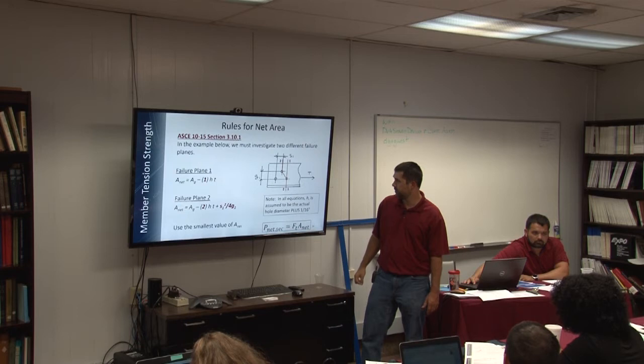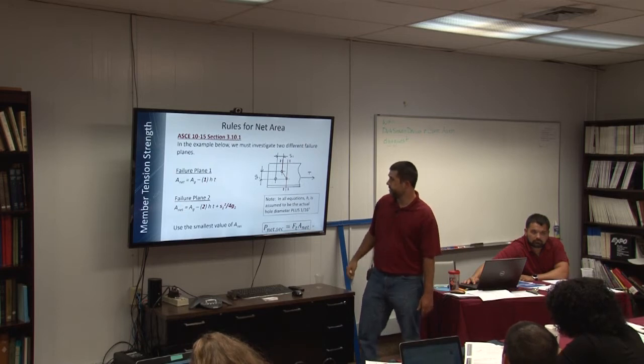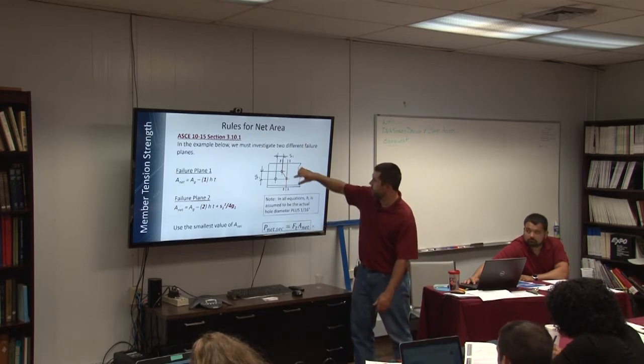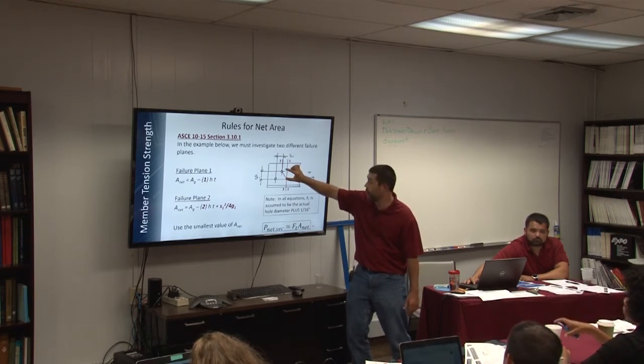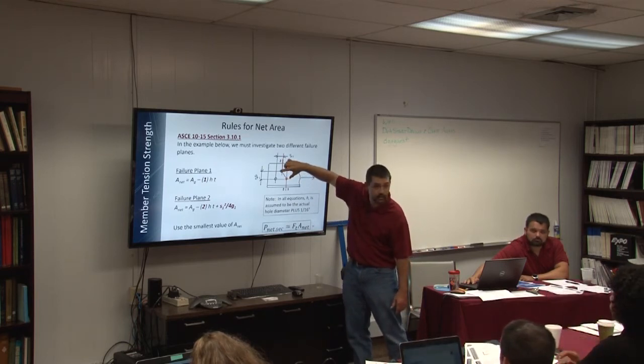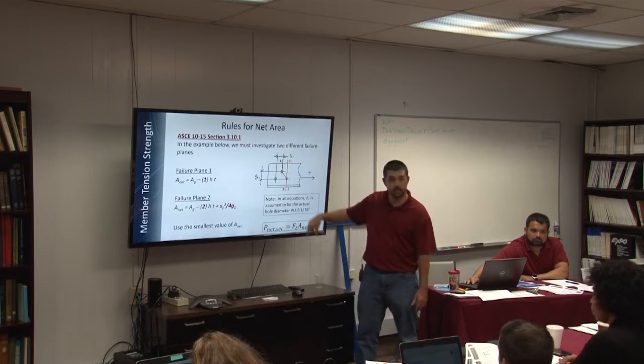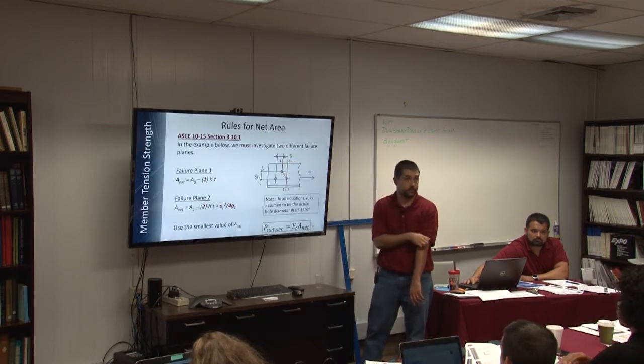Does the second one usually control? It's going to depend on, essentially, the more these two holes are aligned, the more that they control. But if you get some pretty wide staggers, then potentially the first one controls.